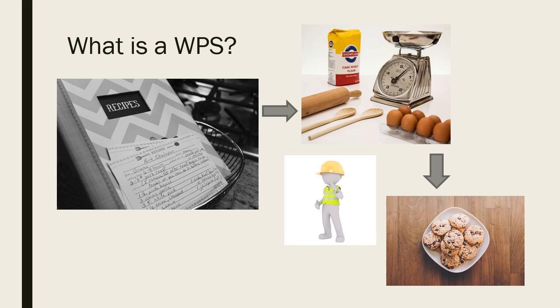It's instructions. It's a recipe that tells the guy making the cookies how many eggs, how much flour, how much chocolate chips, whatever. It tells him, hey, I'm going to weld this kind of carbon steel to this kind of stainless steel. I'm going to use this filler material, this shielding gas, this backing gas. This much preheat, or this is going to be my heat input. You're telling that welder everything that needs to go into that document to deposit sound weld metal into that joint. So basically a WPS is just a recipe.